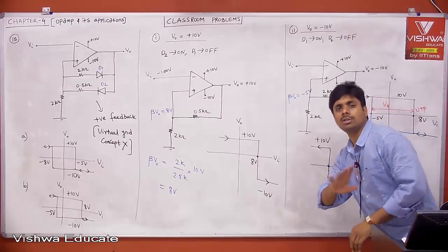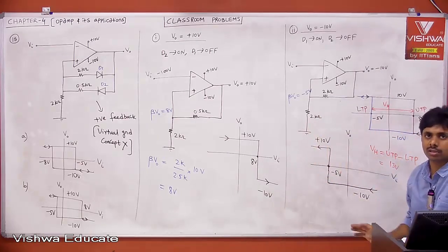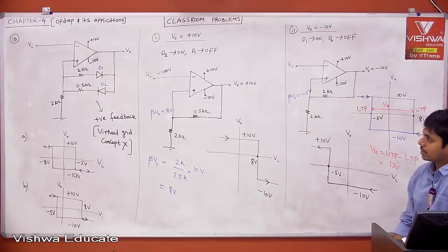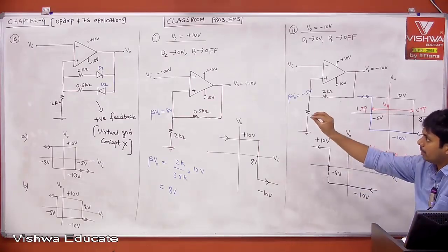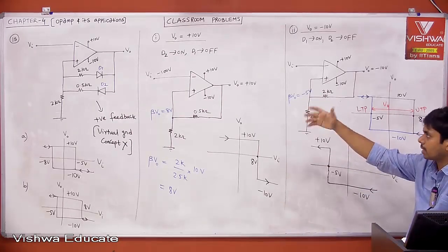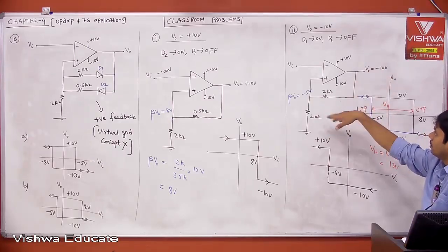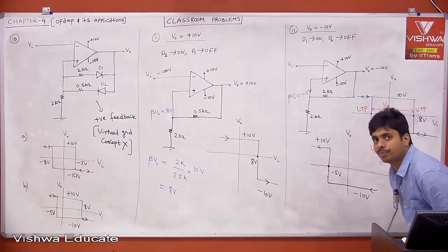See, for all positive feedback problems, this is the technique, or this is the methodology. Simple. Once you know that this is a positive feedback problem, just define your output voltage as one of the power supplies. Then derive the circuit, then get the V0 Vi relation, then the next derived circuit, then get the V0 to Vi relation, and you'll get the answer. Okay? Done. Take it.